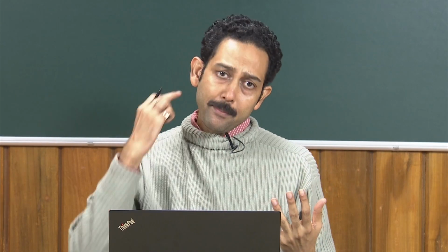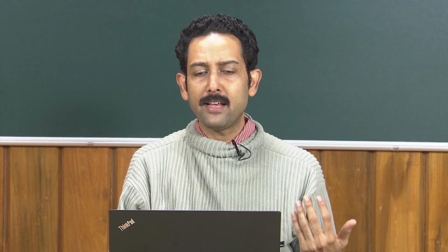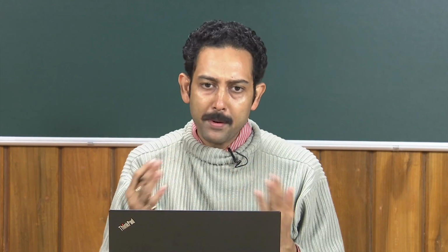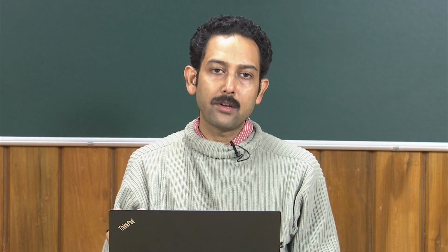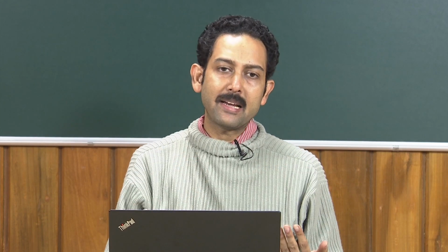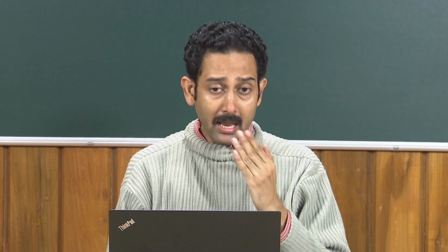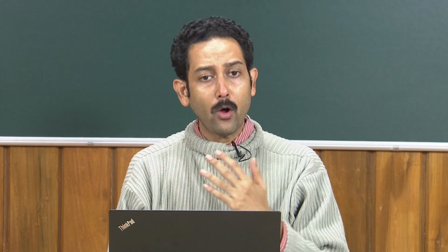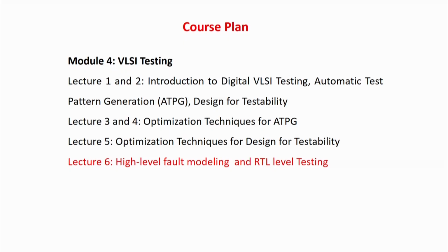So, why gate level? Because till the advent of very sophisticated circuits like NOCs and SOCs, more or less we could handle VLSI circuit testing and design with quite a good level of optimization. The cost required to implement the algorithms, the time required to generate the test patterns, and the time required to do the verification were quite reasonable at the gate level. But when NOCs and SOCs came into the picture, even the gate level with a structural fault model started blowing up.